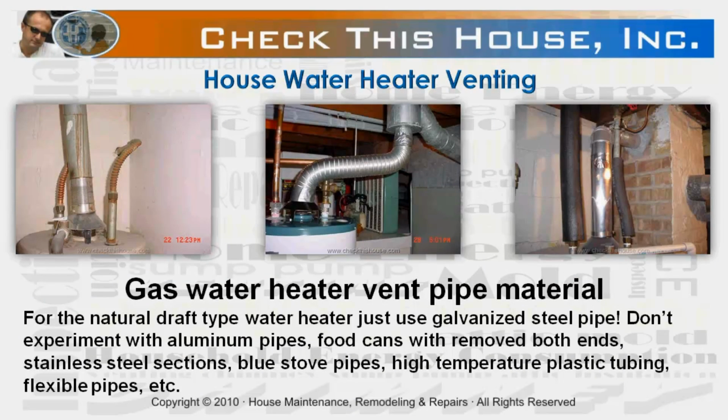Now let's talk about the second component of the water heater venting system, the vent pipe itself. First, the material. For the natural draft water heater, you should be using galvanized steel pipe only. Do not experiment with aluminum pipes, food cans with both ends removed, stainless steel sections, blue stove pipes, high temperature plastic tubing, flexible pipes, etc.